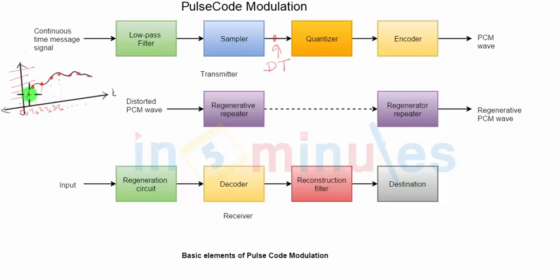So at the output of the quantizer, we have discretized the amplitude axis also. So at the output of the quantizer, the signal is still not available in pure digital form. The signal has the sample values taken at discrete time instances, and all these sample values are now assigned some fixed levels. Hence, I can say that the output of the quantizer is something which is discretized in time domain. It is a discrete time signal.